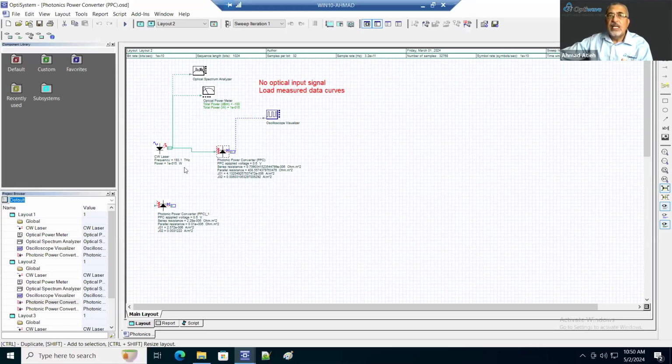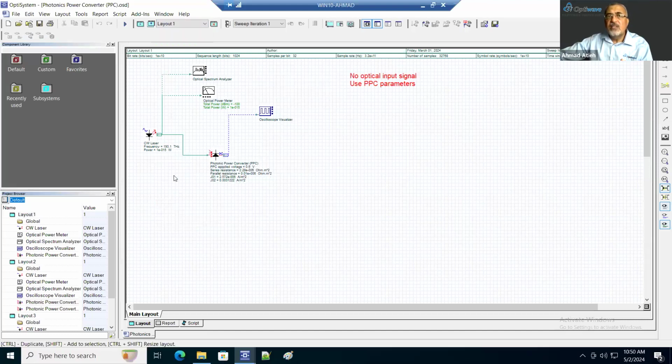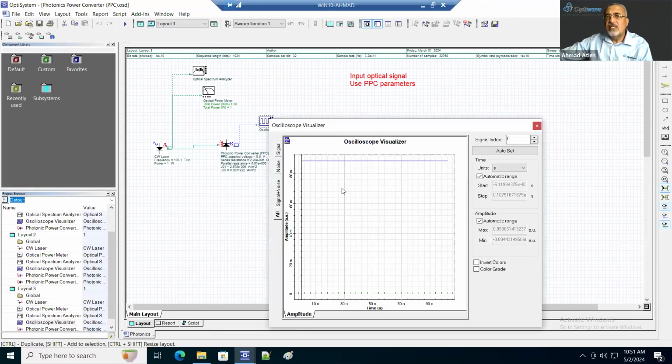Now, in these three examples here, for this component we use zero current, so this is called dark current. And this one here is where we apply 1 watt onto the surface of the device. And you can see here, with 1 watt at the surface, we can generate about 80 or 90 milliamperes from the device.